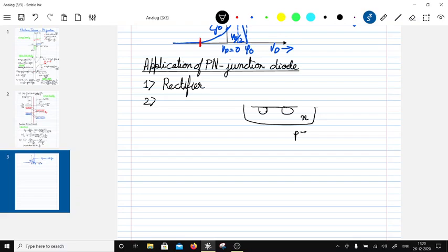This is going to be p plus, and the channel is going to be p here. This is going to be the gate, and then source, and then drain. Then you can put in a body terminal here, n plus, so this will be the body. So this sits in its well, and this p substrate is connected to the most negative, which is going to be 0 or ground. So this junction is going to be reverse biased. This causes the device to be isolated from the bulk.